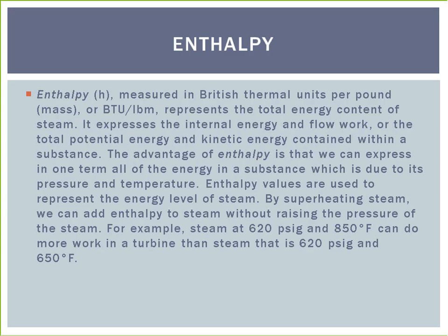Another important concept commonly seen with BTUs is enthalpy, measured in British thermal units per pound mass. Enthalpy represents the total energy content of steam. It expresses the internal energy and flow work, or the total potential energy and kinetic energy contained within a substance. The advantage of enthalpy is that we can express in one term all of the energy in a substance, which is due to its pressure and temperature.